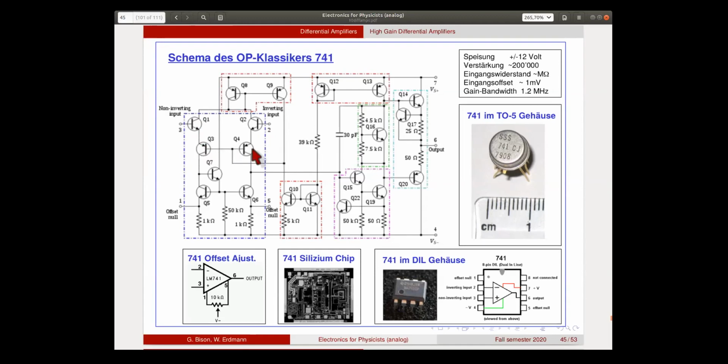And these are the actual modulating transistors, but they're not connected in the way that we've seen on the previous pages. They're used in a common base configuration. So the base is sort of fixed, and the inputs modulate the base emitter voltage of these transistors. Okay. So this is a slightly different use of the transistor, and this modulates then the currents that flow down in these two branches, but the rest is pretty similar.